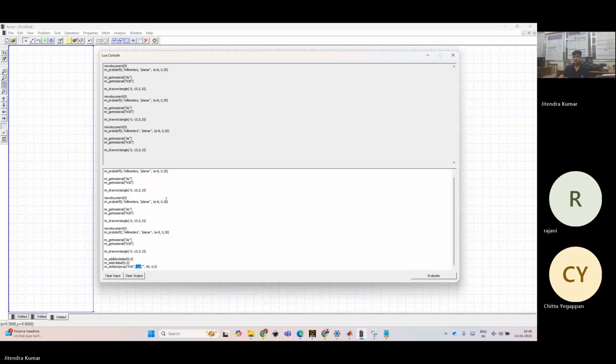Now, these quotes are there to assign any coils. If there are any coils, they will have current circuits, something like that. That should be there, right? So that assignment has to be there. But in a permanent magnet, no coils are there, so we could keep it blank.